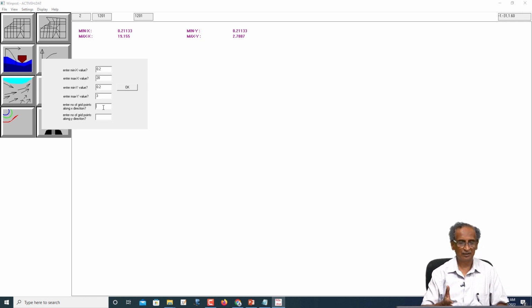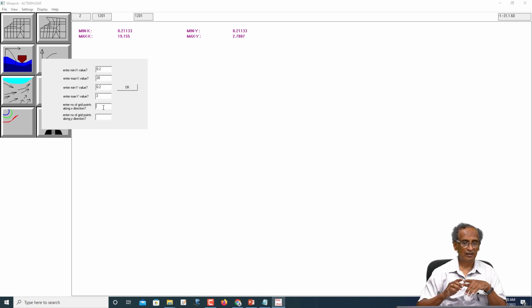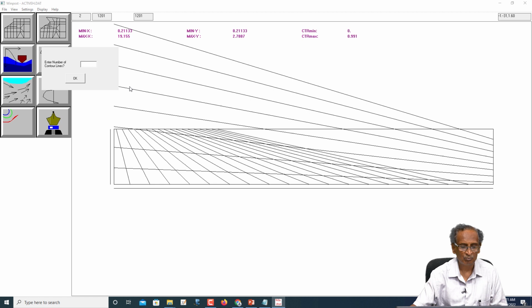This program is going to generate the data in the XYZ format. X and y are the nodal coordinates, and z is the contour value, and it can interpolate by providing a grid of values. Let's say along the x axis I want 20 points, and then along the y axis I need 10 points. Okay, you say yes, and then the contour lines, let's say 10.